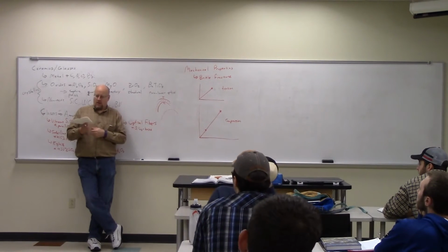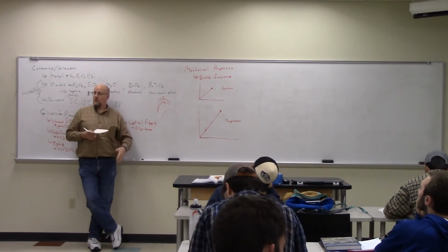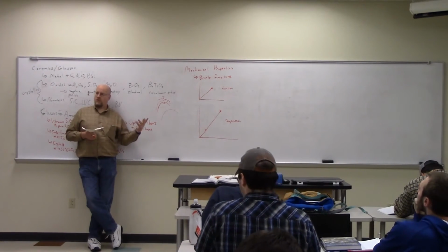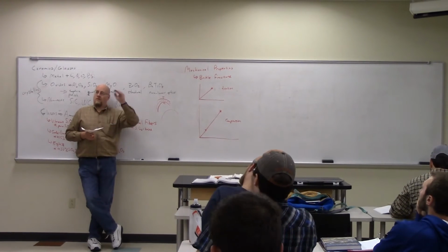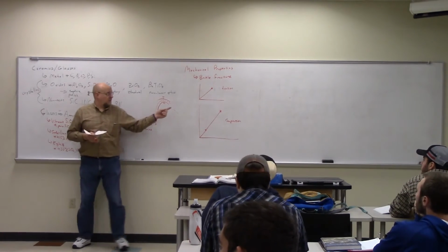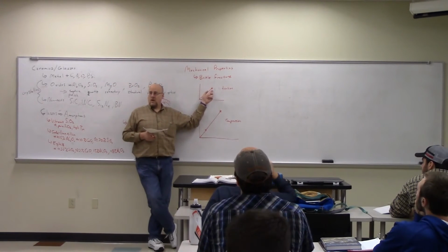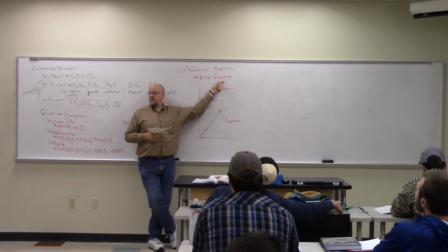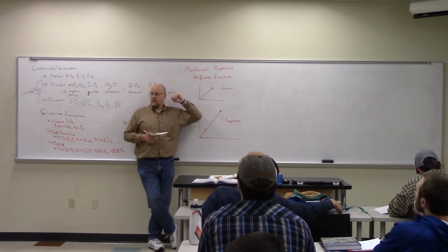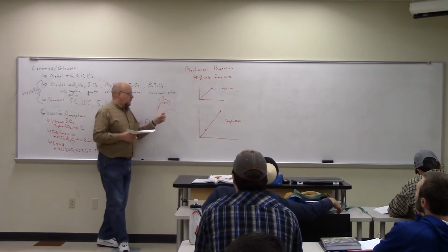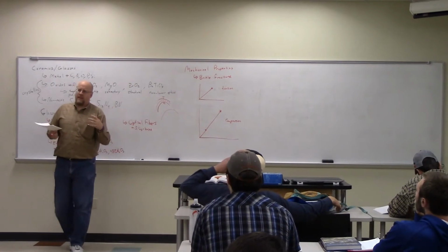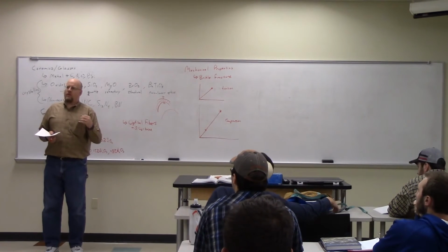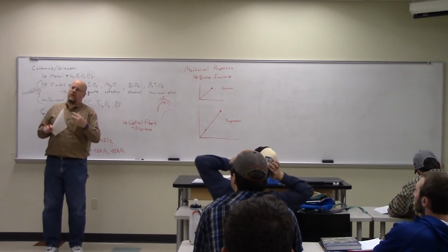The other thing is optical fibers are typically very polished, so the number of cracks on the surface is significantly reduced, which gives them even greater strength. The difference between a regular piece of glass in tension and a polished piece of glass in tension is substantial. It's still the same line, but you get further up. If you polish it, you've got fewer cracks to initiate a premature failure. Those are the two things. And then they also sheath them, so they're inside another material, so that even if a crack tries to open up, there's something else there to keep it closed.